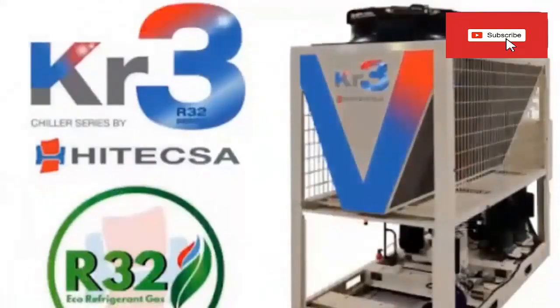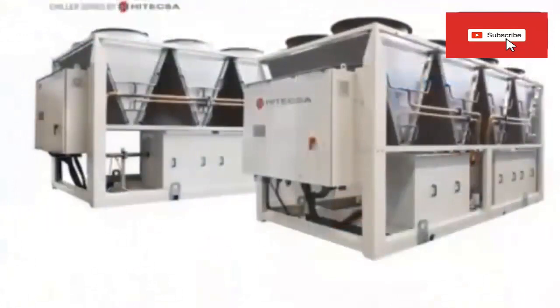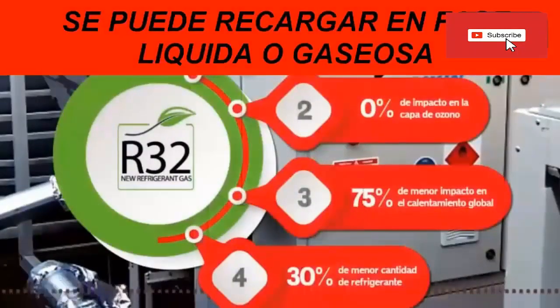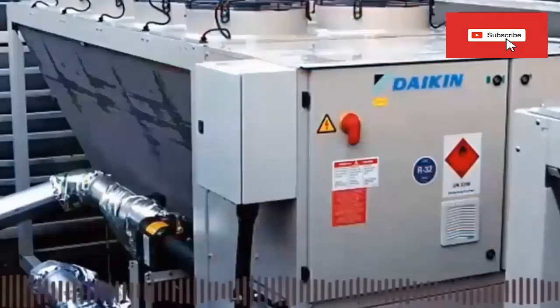5. R32 has better efficiency and around 10% more capacity than R410, depending on the application and system design. 6. The charge amount of R32 refrigerant is about 30% less compared to R410. 7. R32 is a relatively inexpensive single-component refrigerant, which means it is easier to recycle. 8. The fact that there is no patent on R32 ensures access and availability through many refrigerant suppliers, ensuring that R32 remains cheaper than its competitors.